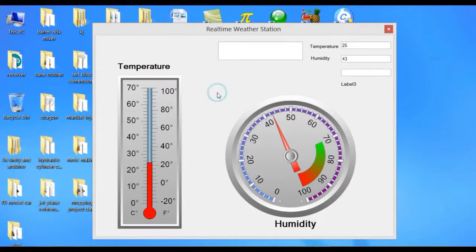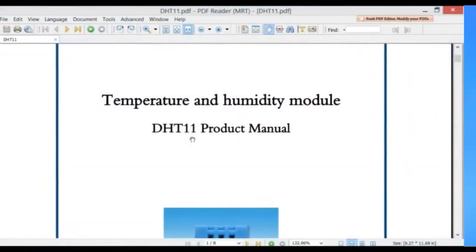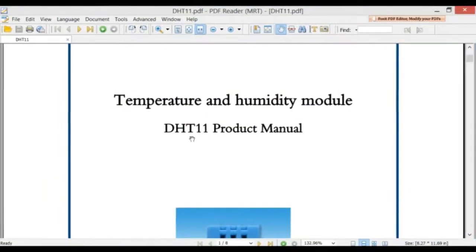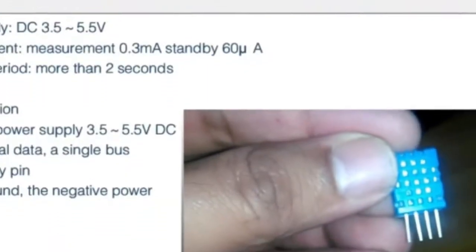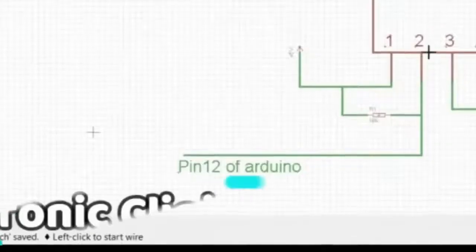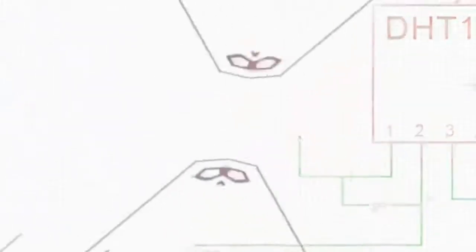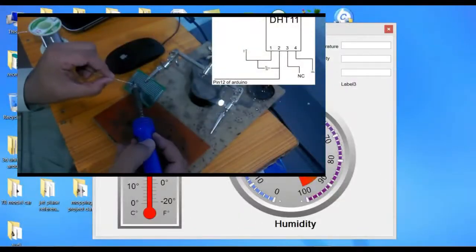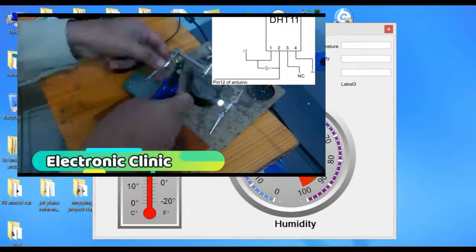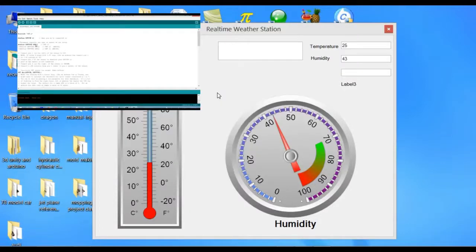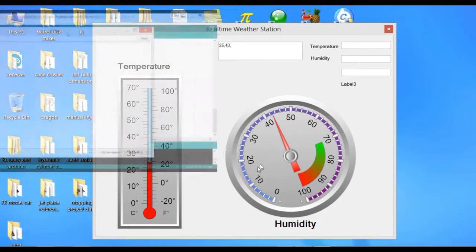Before we start working on this project, first let's make a plan for how to complete this project successfully. Number one, start with the sensor or sensors that you will be using. Study the sensor's data sheet, its voltages and the amps it will be needing. Number two, make a circuit diagram. Number three, soldering or assembling the components onto the breadboard as per your requirements. Number four, controller programming. Number five, checking the code.